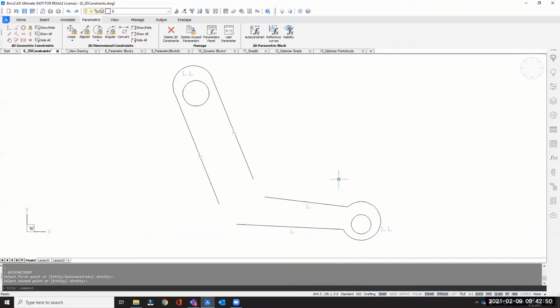We have this and this. That's fairly easy. You just need to make sure that you have connected all the points that you wish to be connected together and always be connected with each other. You would see that these symbols would be appearing, meaning these are the constraints that you have been adding to each of the entities. You would see that when you hover on one, the entities that are involved are also highlighted for you.